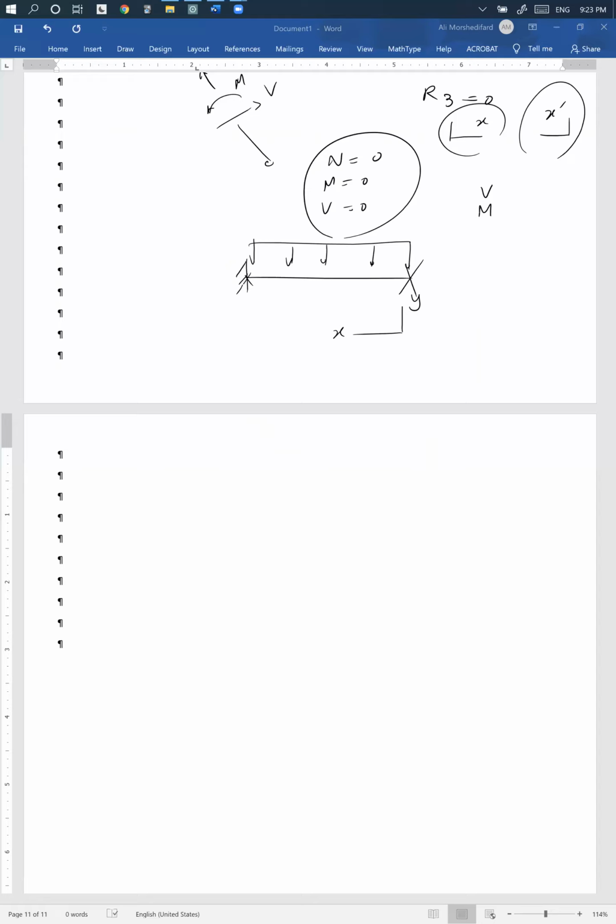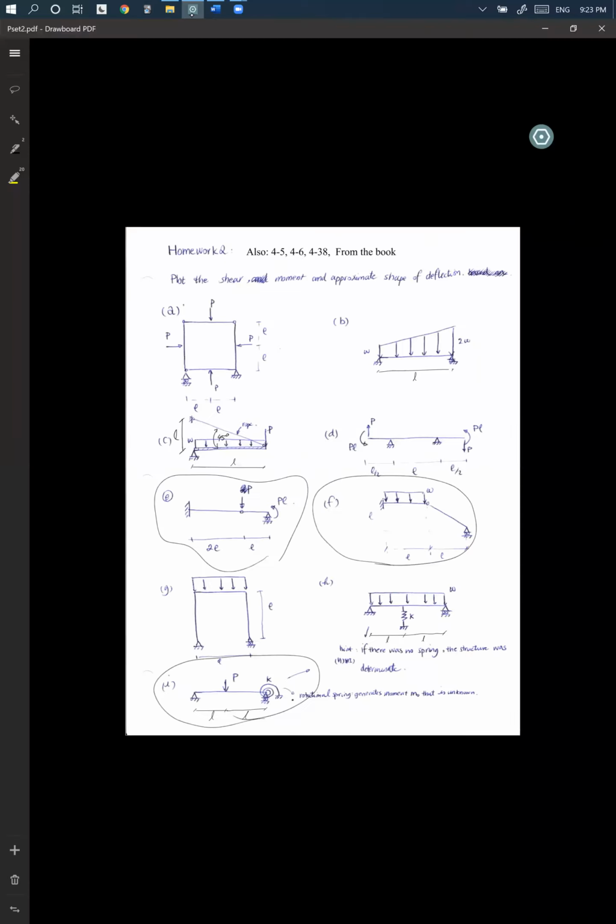I'm good. So for the spring problems, H and I, to solve for the reactions, do we have to do the slope deflection method, or superposition? No. So for these problems, as I think I solved in I1, I said you can just assume that there's a concentrated moment here, call it MR, and solve your problem.